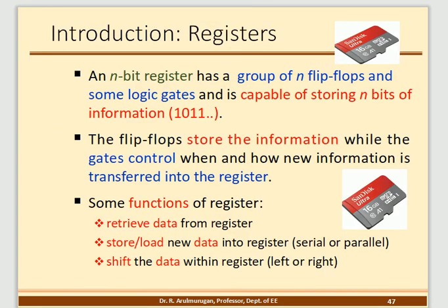A register is nothing but a memory element. An n-bit register means n flip-flops, so 4-bit means 4 flip-flops and 6-bit means 6 flip-flops. An n-bit register is a group of n flip-flops and some logic gates, capable of storing n bits of information.